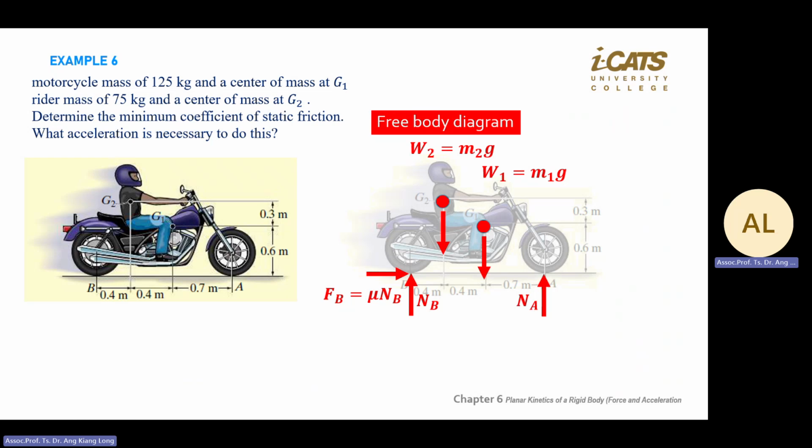Okay, there's a friction force. And the direction, you refer to the wheel direction. This wheel rotates clockwise to move to the front. So there's a resistance force to the friction. So friction is pointing towards that direction. And this one, I write NA near to 0 because you do a wheelie. The front wheel moves up, right? Okay, so if you know that NA is 0, remember to write this in your answer. This one usually is a free mark if it's 0.